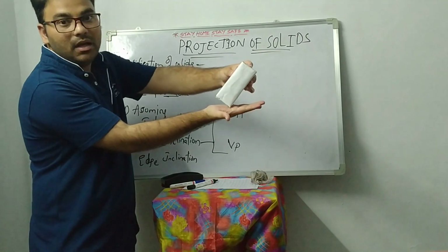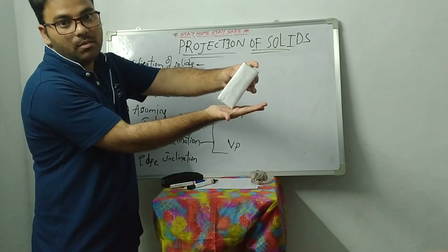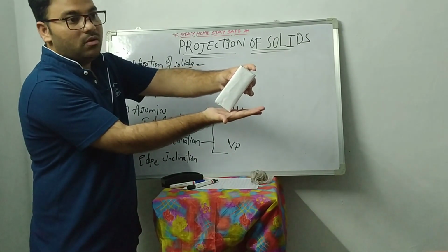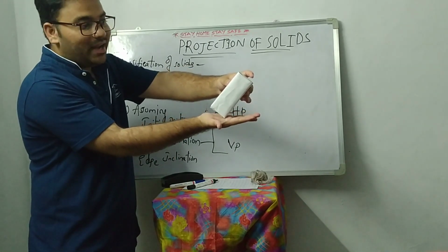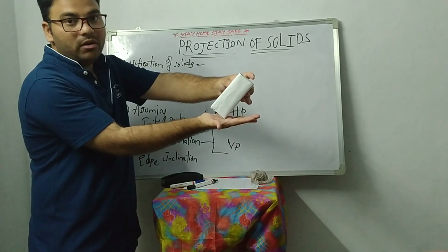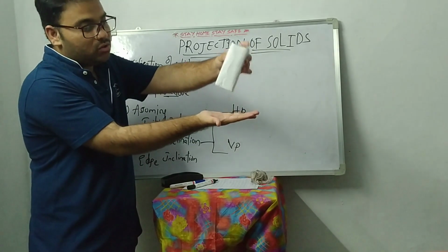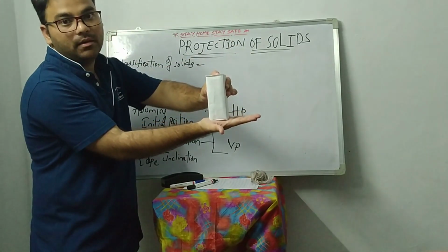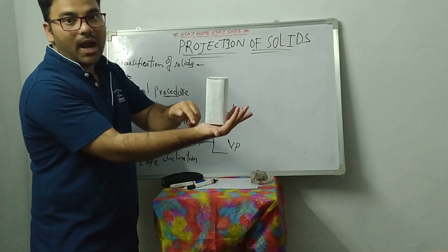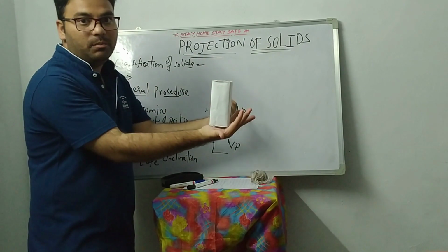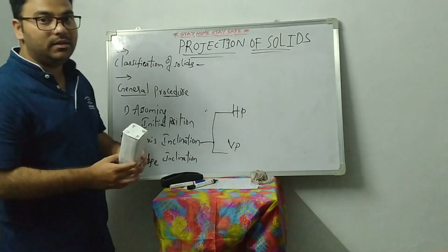Now this is the condition that will be given in the problem. So we are going to draw the top view and front view for this problem. This is the second condition, axis inclination. For the first step, if the axis is inclined to the HP, then tilt the axis perpendicular to the HP. Then you can see the true shape of the base in the HP and the rectangle face in the VP.